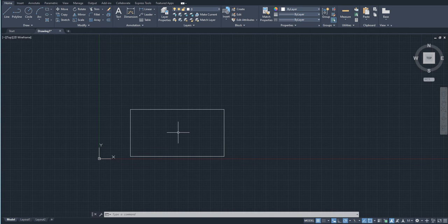The next thing I want to show you is the mouse pointer. I'm sorry I didn't discuss this earlier, but the mouse pointer, as you can see, consists of a square with four lines in it: a line upward, a downward, left side and right side. This is the cursor for the mouse when no command is active. But for example, if I activate any command, if I go over here and press on Line, you see the command line is activated and the shape of my crosshair has changed. To escape the command, to close the command, I just press Escape once.